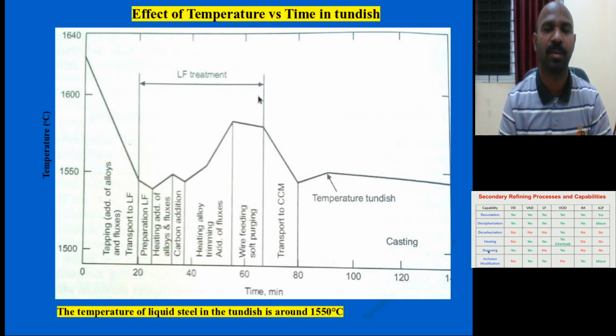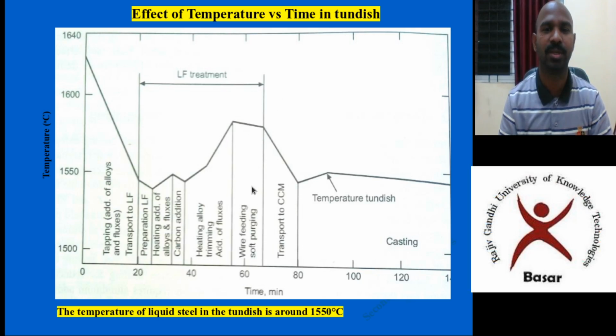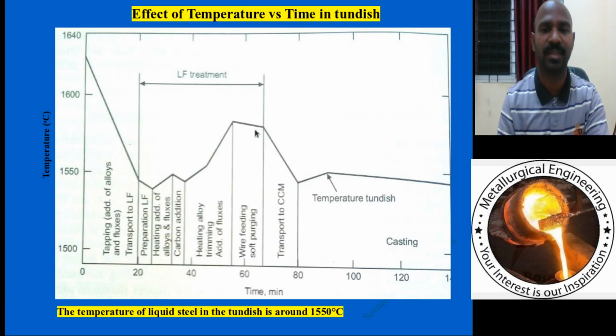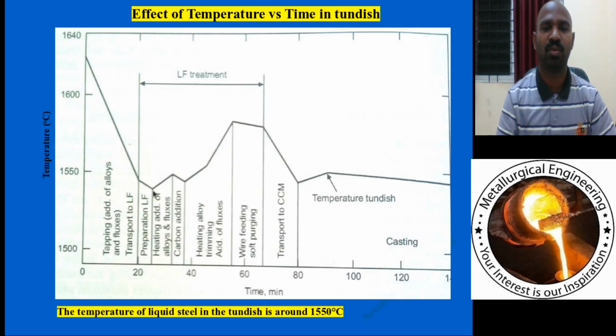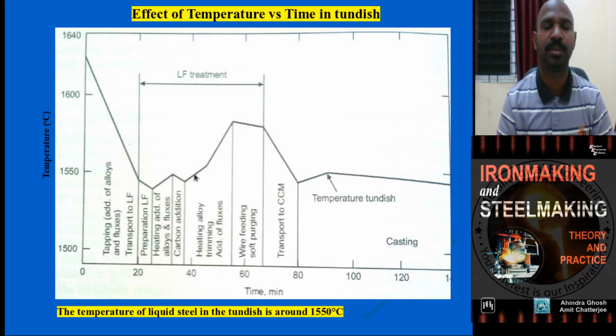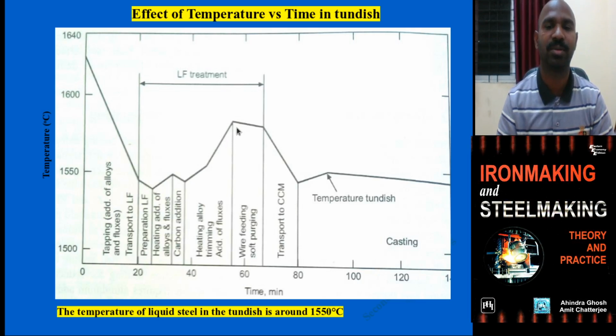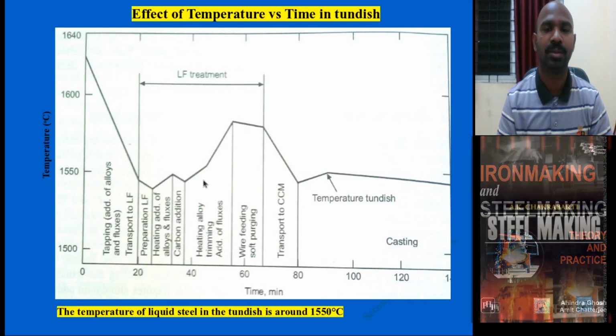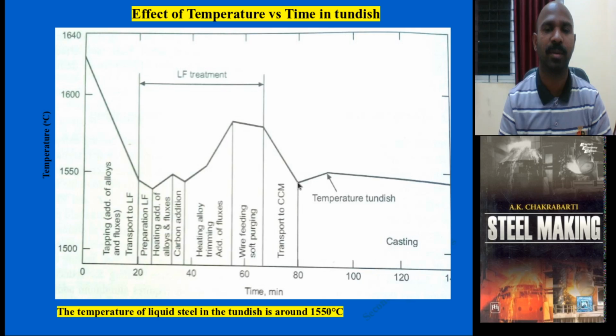For example, for deoxidation, you can feed aluminum wire so that deoxidation takes place during the ladle furnace treatment. After the temperature drop within the ladle furnace, the temperature of around 1540 is increased to around 1580 degrees Celsius, and when it is moved to the continuous casting mold, it is 1540.